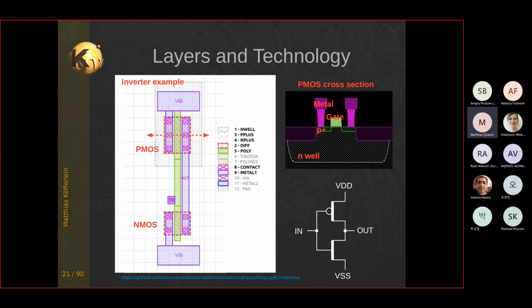You add filler cells or spacer cells or special tap cells between. This is typically a task of a digital flow then, to make sure that the N well areas are well connected to the VDD. And this is important because if you don't do so, you will get latch-up effects, and your device will probably fail, or it will suddenly go into latch-up and then be damaged.